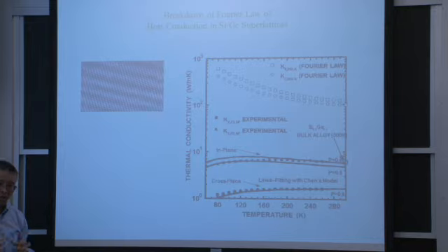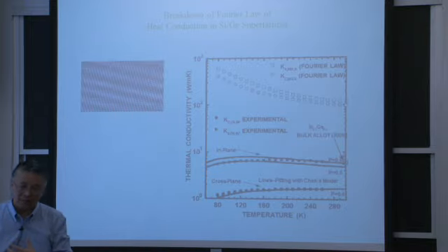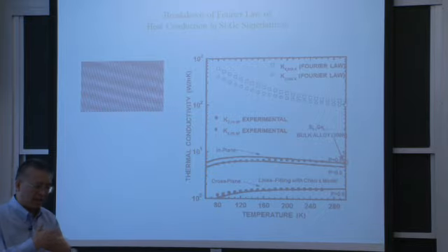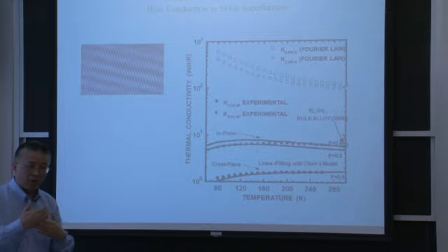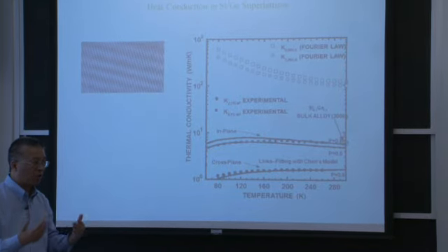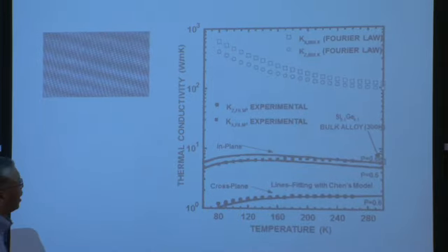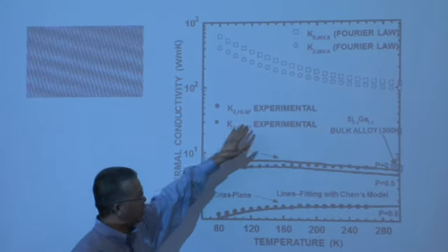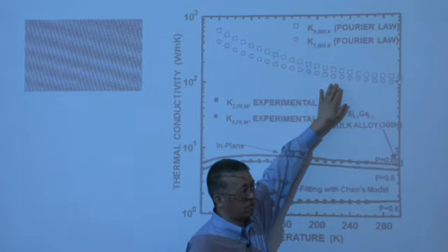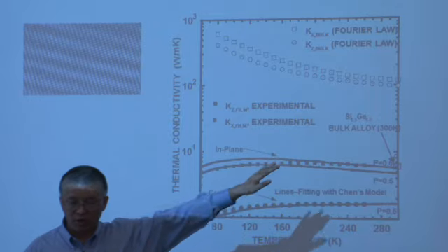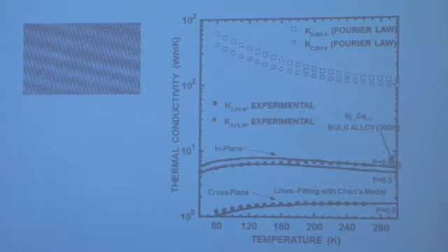When you measure thermal conductivity, you can take silicon for one layer and germanium for the other, so you have heat transfer through parallel layers. Then you can use thermal resistors to find the effective thermal conductivity. If I take the silicon and germanium thermal conductivities, I will predict the equivalent thermal conductivity shown by those open circles.